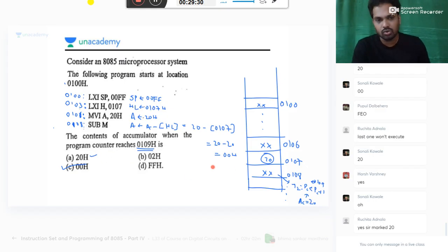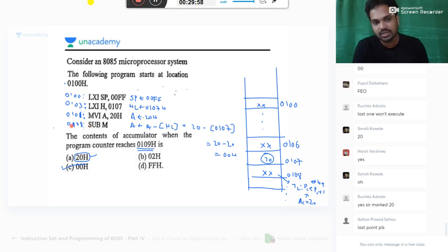So I told already 20 is also the right answer. Another way is by the end of this instruction, we assume without fetch-execution overlap, which may be done internally, but we assume that this is also the right answer, but in the actual sense it is 20 only. So both can be right answers in this case, because after execution originally this happens in the next machine cycle.